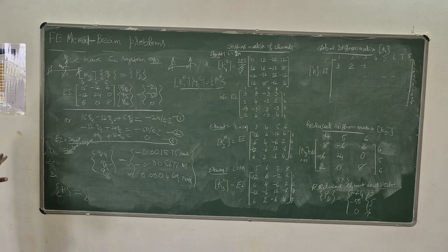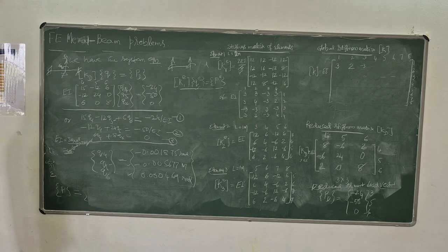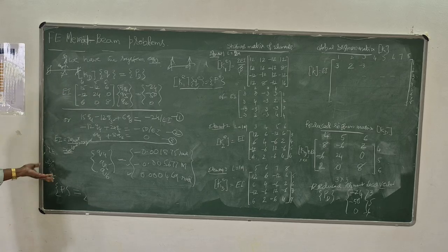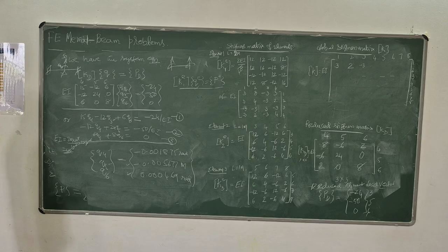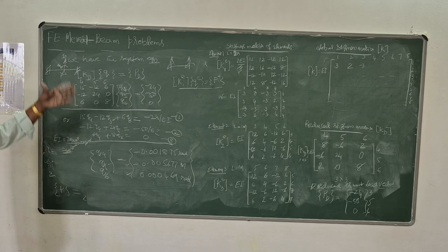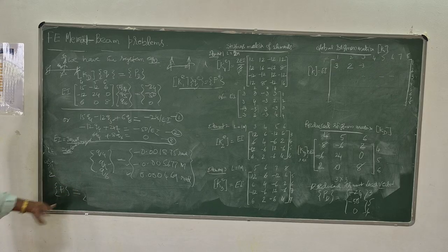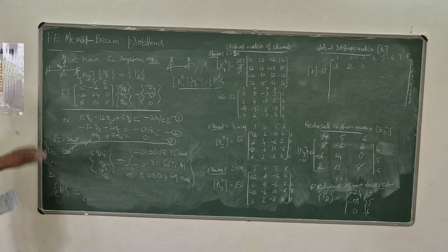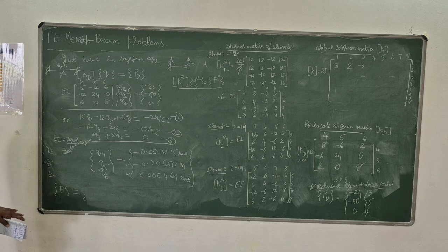So with that, you can calculate moment and shear at any point in the beams, as well as at the nodal points. If the problem arbitrarily asks to determine the slope and deflection at a point, you select a node. That's very important. You have to introduce a node at that point and generate like this. So the element will become a superparametric or subparametric element, depending upon the number of increased or decreased nodes, rather than isoparametric.